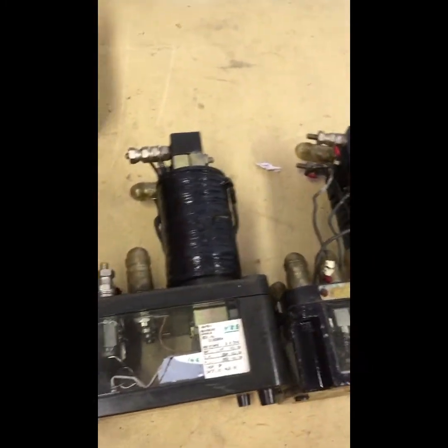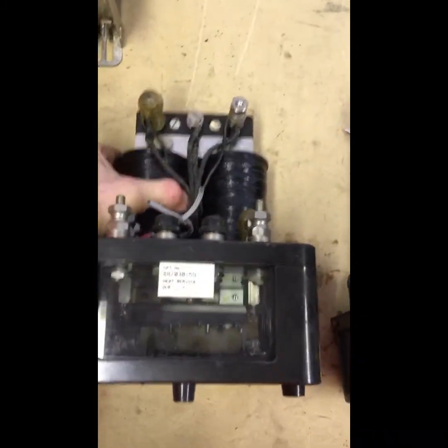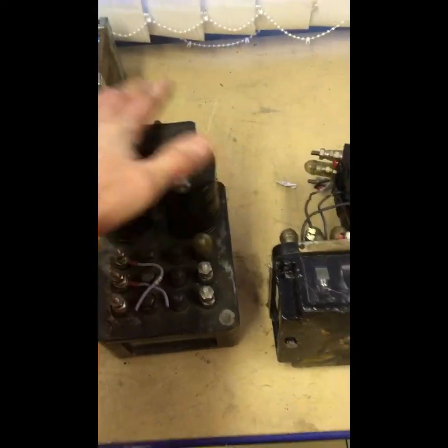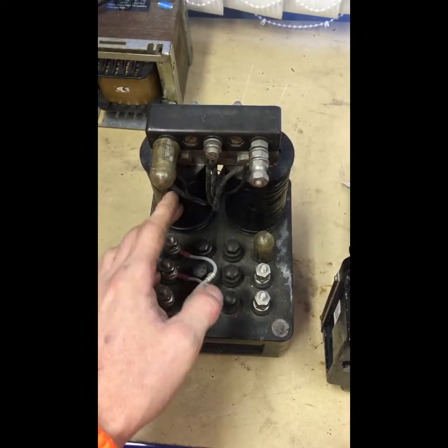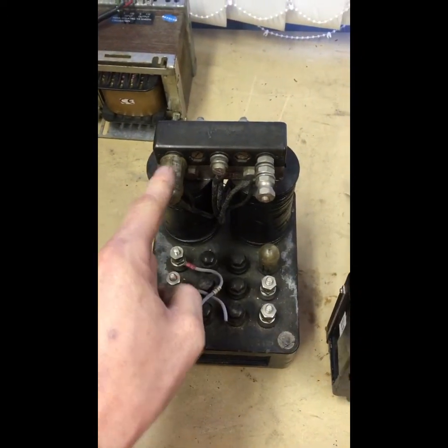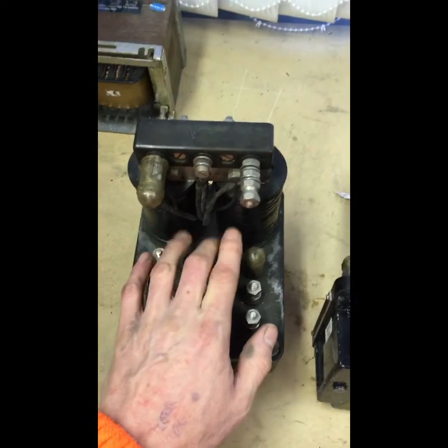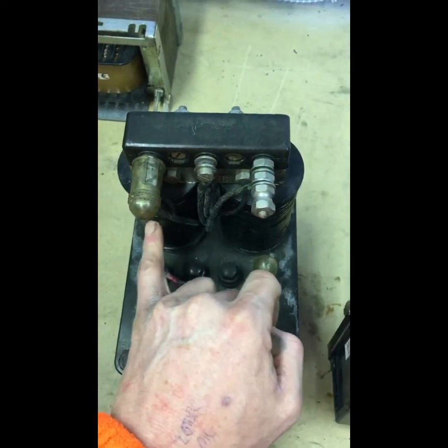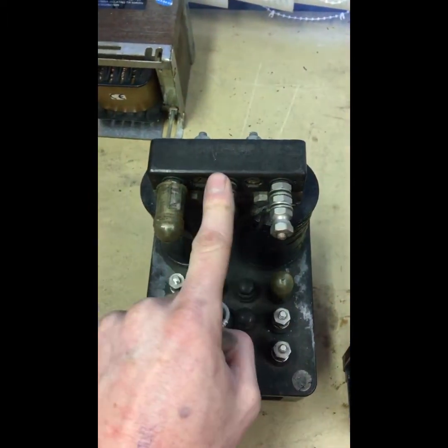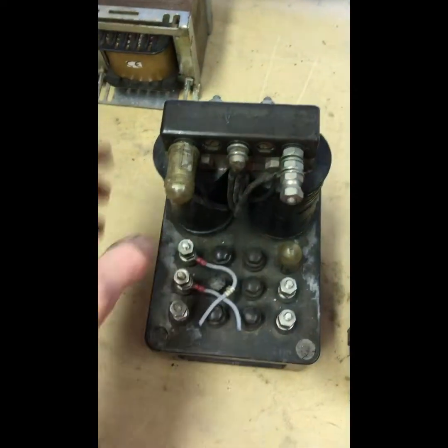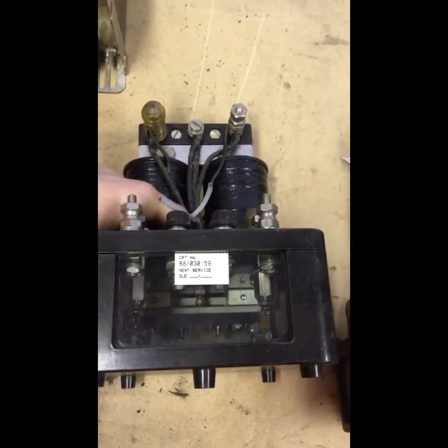An additional DC track relay consists of, in the older form, a case, contacts in, two coils on top, a coupling bar through the centre, and you'll notice each coil is connected on its input side to a central stud terminal, then to the other coil, and then back out. And it was known in the past, if one of these coils went down and had an open circuit within it, you were able to take that coil out and bypass it by taking the strap and putting it onto this, which meant only one coil would be in use. That was an emergency get out in the past. It's not something you would do nowadays. You would change the relay.